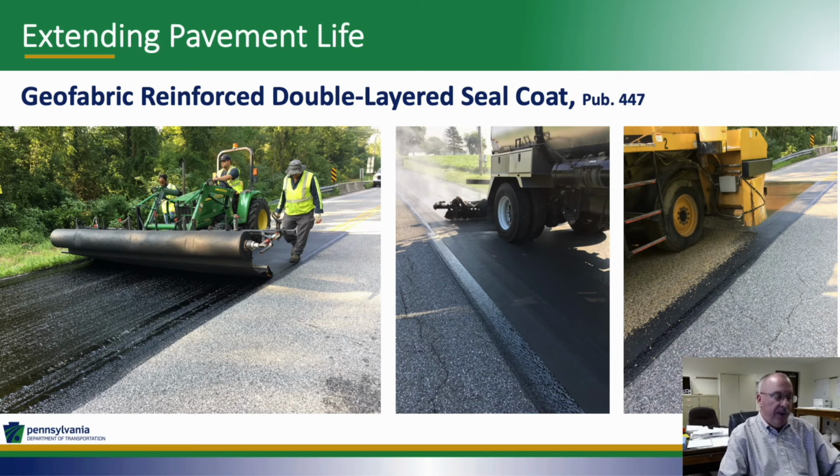Dover Township and PennDOT's New Products Committee recently completed a pilot project on the use of paving fabrics under a double seal coat. That project was a success, and the process, titled Geofabric Reinforced Double Layer Seal Coat, is now an approved process and can be found in PennDOT Publication 447.